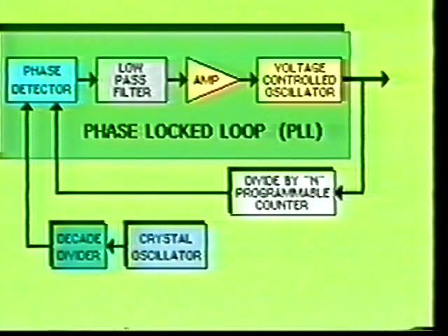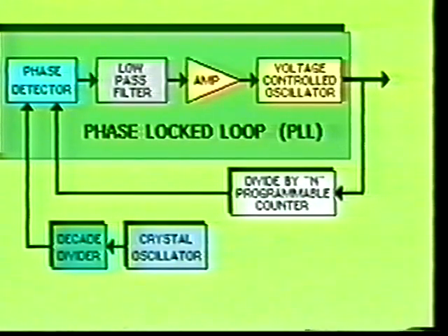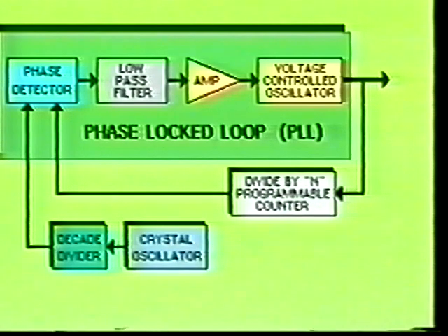Many of today's transmitters make use of frequency synthesizers to generate a highly accurate and stable frequency to be used for the transmitted carrier signal. Frequency synthesis is achieved by employing digital IC circuits to obtain the exact frequency from a single fixed frequency oscillator circuit. As you can see in this particular circuit, the phase lock loop IC is used to synchronize the output of the transmitter oscillator with that of the crystal-controlled oscillator's output, both in phase and frequency.